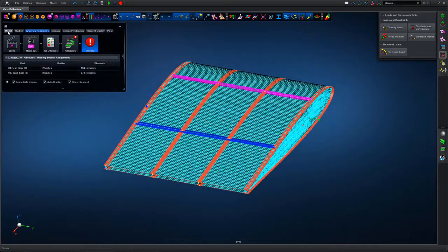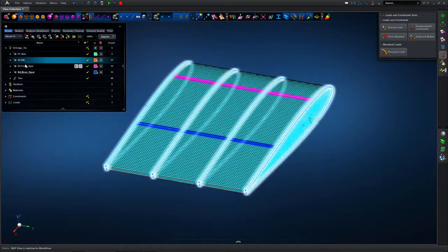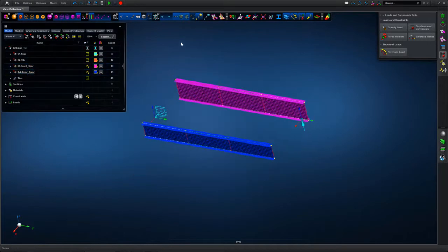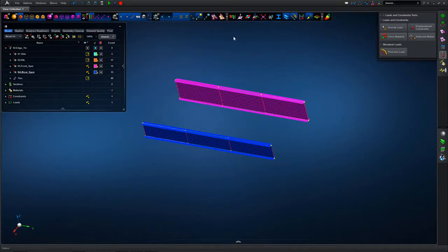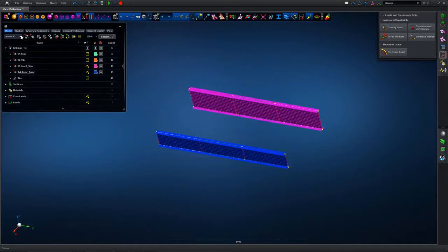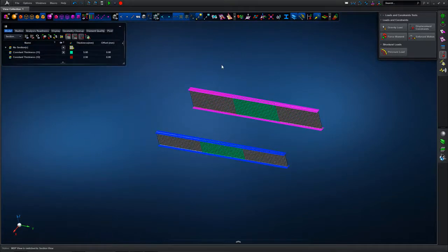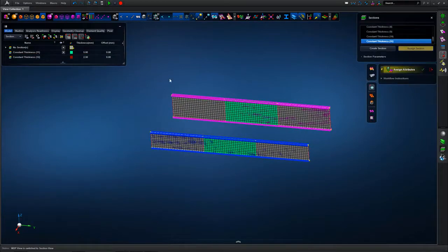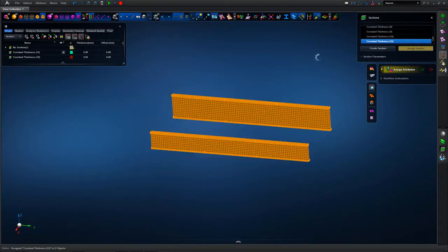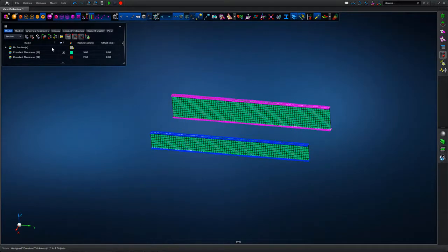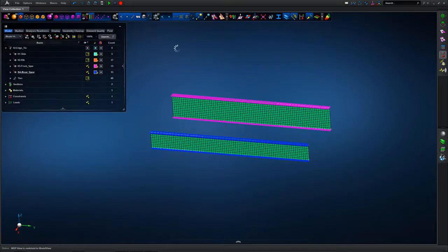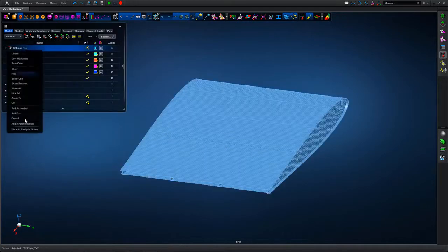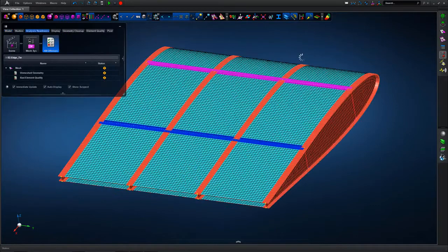So we go back into the model, and from prior knowledge, we know that we potentially have a problem with the spars when they were split. So looking at those regions and going into section view, we can see that the grey areas have no section defined. So it's a simple case of redefining the spar property for the full region, and then going back into the full assembly, and then running the analysis readiness check again.